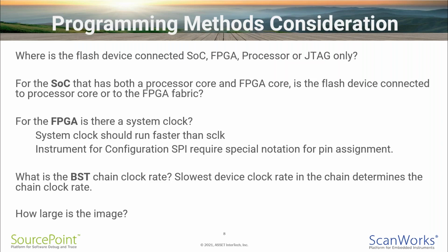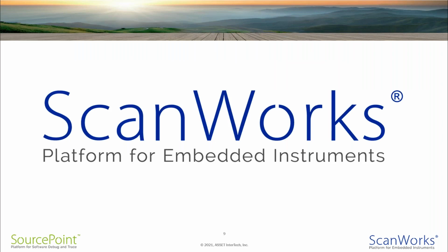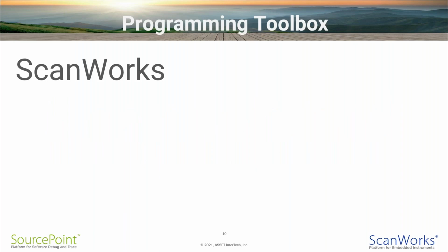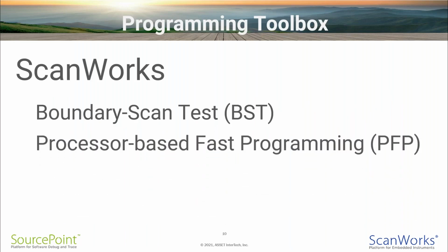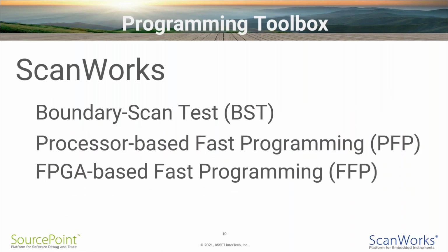We constantly work with customers that spend 30 or more minutes trying to program flash on a single device. That represents a significant cost in development and in production. So let's talk about ScanWorks. ScanWorks is a premier product test platform, but many users aren't familiar with the powerful toolbox provided for fast flash programming. The ScanWorks toolbox for programming includes boundary scan test, processor-based fast programming, and FPGA fast programming.